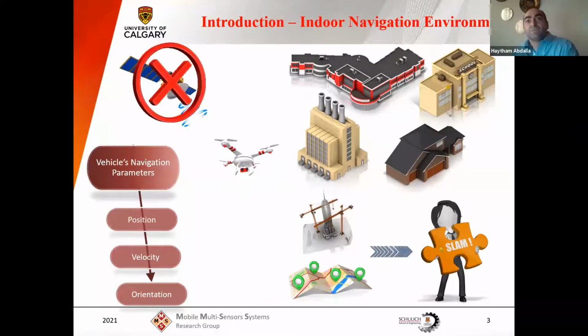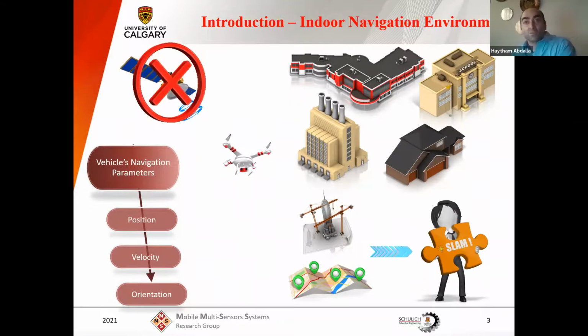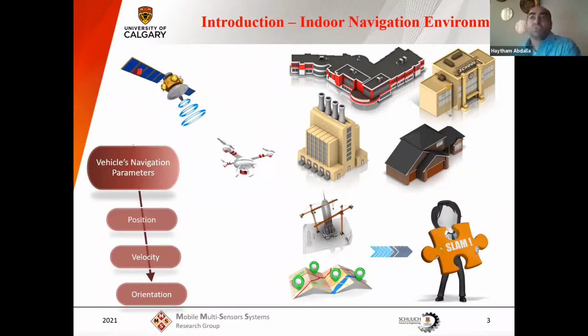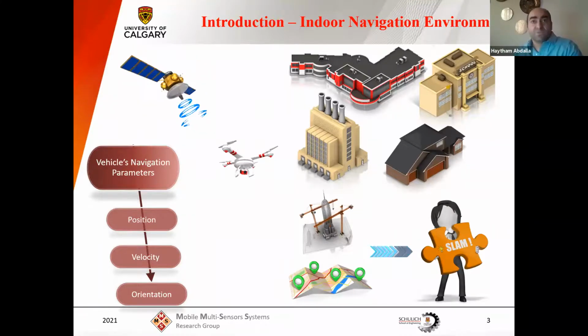If building the map or navigating inside this environment takes more than 20 minutes, it should return, okay? Because there is a return trajectory until it goes outside. So if it reaches 20 minutes, it will stop the mission. Or if no gaps are detected, it will stop the mission.